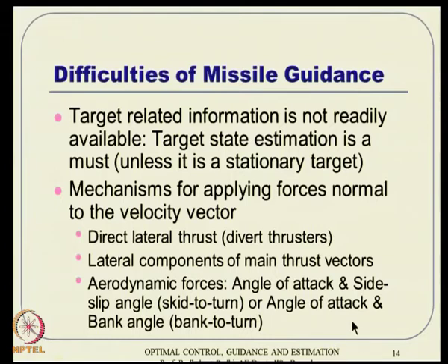So that means you can consider the side slip angle as something like angle of attack, and both angle of attack and side slip angle can be generated utilizing the control surface deflections, and that concept is called skid to turn. And suppose that mechanism is not there, the vehicle has only 2 big wings and all that, that is also possible, and especially for long duration practical things, typically people do that to minimize the drag.